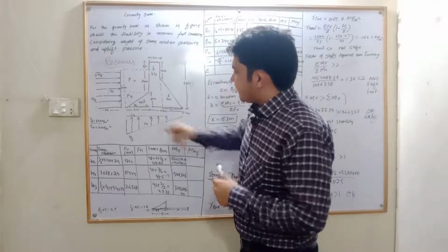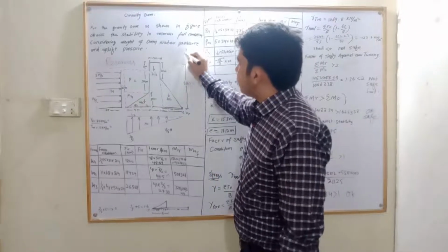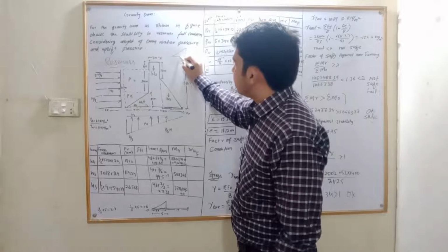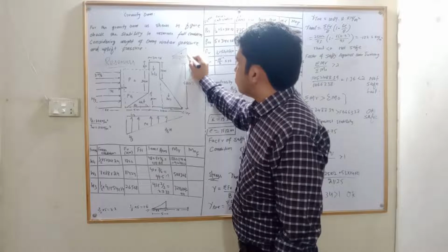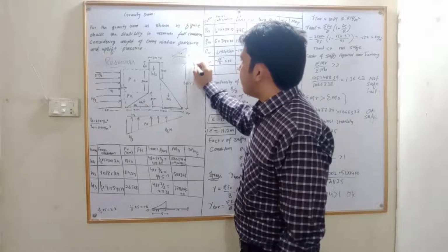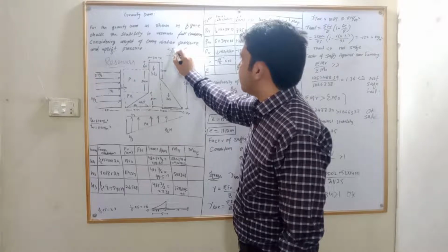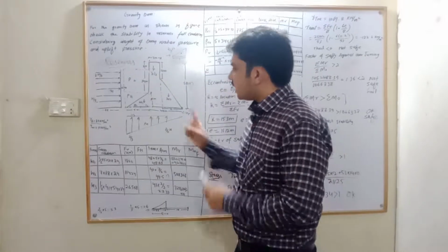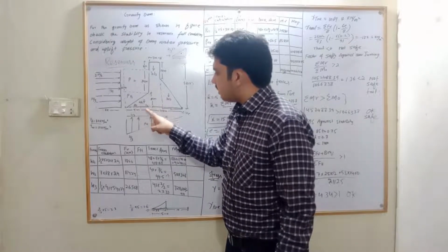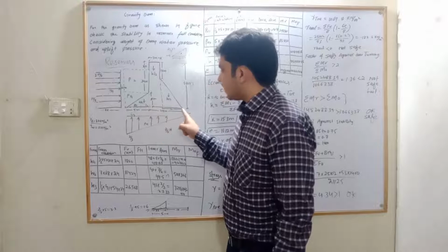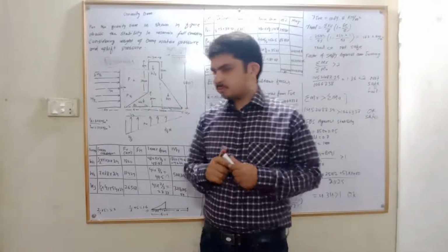Okay, now if we are interested in the W1 center, it is necessary to know how to find the center of the triangle. This is the center of the triangle, and this is the total length L. If we measure from this side, it is L divided by 3. If we measure from this side, it is 2 divided by 3 multiplied by L. Now we are interested from this side, so we will multiply 5 by 1 divided by 3, plus 48, because this is the additional length.